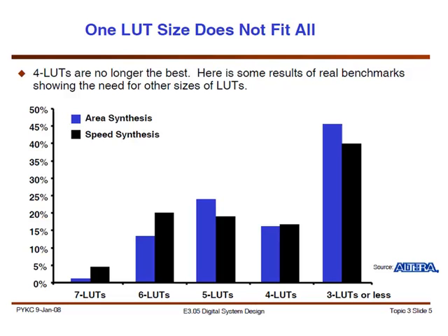If you think about it, if you want speed, what you want to do is pack as much logic into a bigger LUT. So you would like to use more 7 LUTs, because if you have NAND gates feeding XOR gates feeding OR gates, you're covering a bigger subtree, and all of the connections between those logic elements would be hidden.